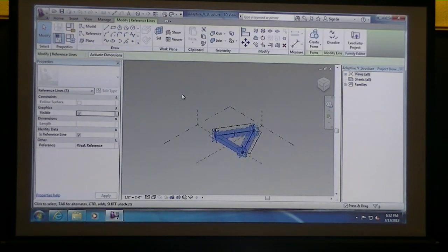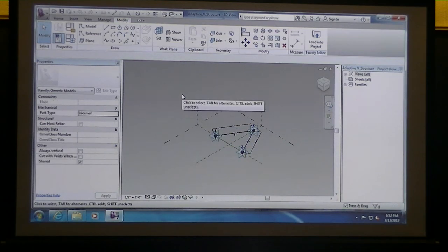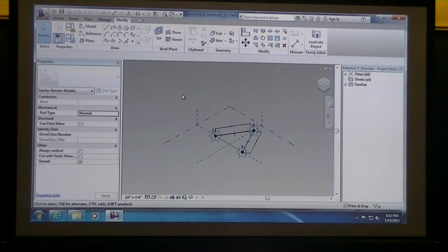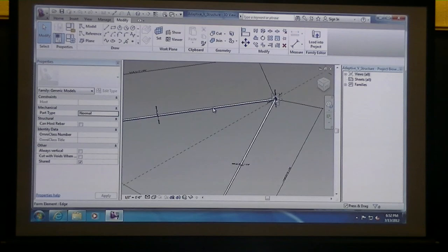But you could actually set up parameters that are materials that can be defined later. So remember, we've been dealing with instance parameters, right? Instance parameters are something that we can set as a default, and when you finally load it into the project environment, you then are able to edit that object or those objects further in the project environment by your instance parameter.